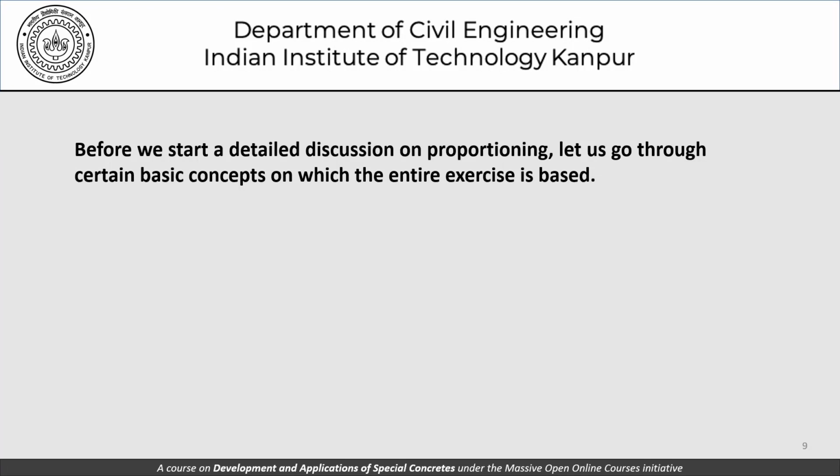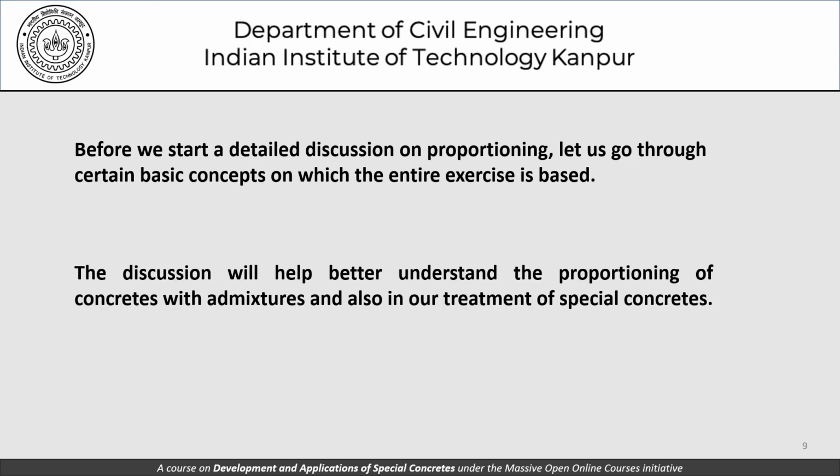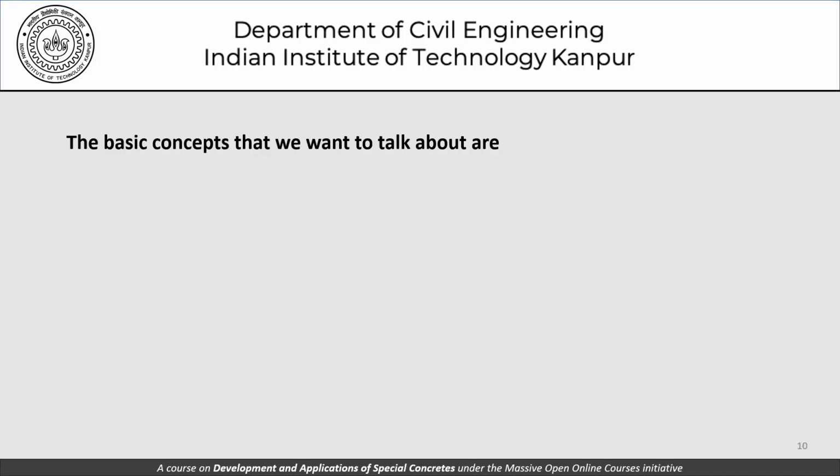But before we start a detailed discussion on proportioning, let's go through some basic concepts which will be very important and will serve as the basis for the entire exercise. The discussion will help us understand the proportioning of concrete mixes with admixtures and also our treatment of special concretes. What are the basic concepts that we'll talk about? One is the water-slump relationship. Remember that water is the only liquid constituent in concrete, and therefore it has a large say in determining the workability of concrete as measured by slump.